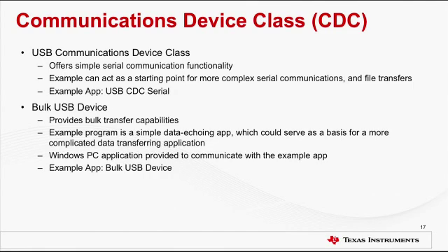The data interfaces are generally used to perform bulk data transfer using bulk USB device. There is an example program in Tiva for C series, which is a simple data echoing app. It serves as a basis for more complicated data transferring applications.